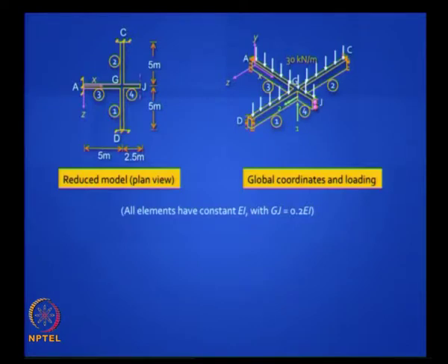So D1 and D2 are the only displacement unknowns. Then at the restraint coordinates, of course you can add all the remaining degrees of freedom. So you have altogether 10 degrees of freedom, 2 of which are active and 8 of which are restrained. Is it clear? I am just demonstrating with one example.